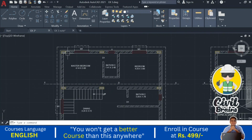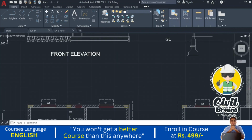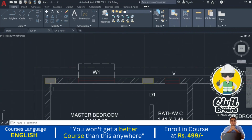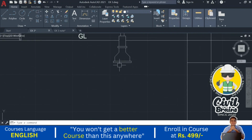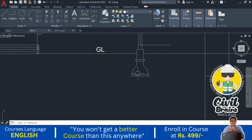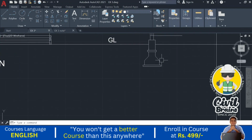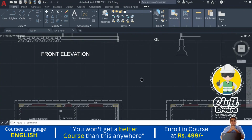Once you cut this one, you just see this wall foundation, correct? And above the wall, whatever is coming, plinth beam, wall masonry structure, everything you just see. So the depth of the foundation footing is 1.5 meter, and you see the isolated footing, and it is connected with the slab. Above that, it is not connected to each other. Here you can see this wall is coming over this footing, but in this section it is showing like this.